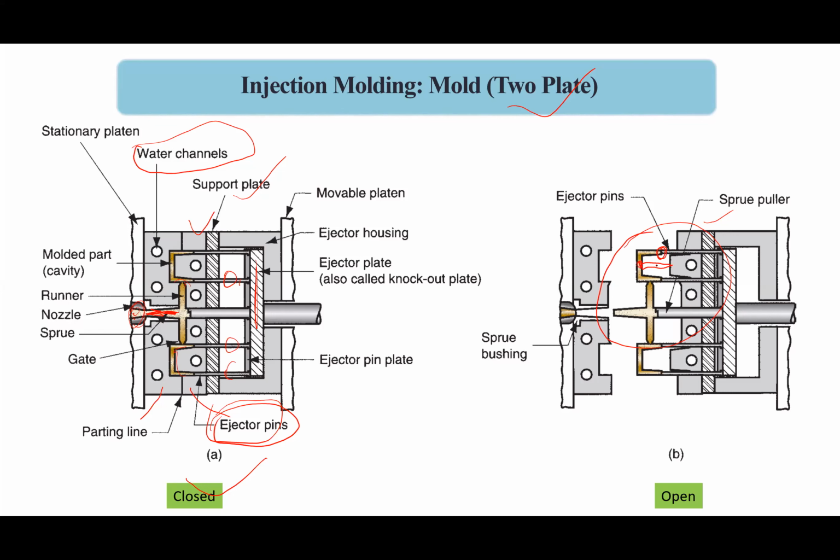So for positioning the ejector pins, you need very careful observation of the material to decide where the ejector pins should be placed. Do you have any question? I'll show you a video of these molds, so things will be more clear there.